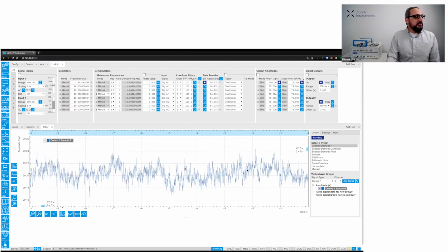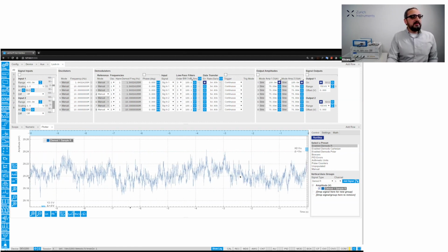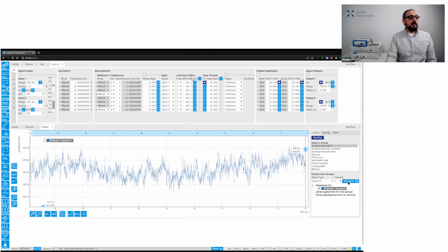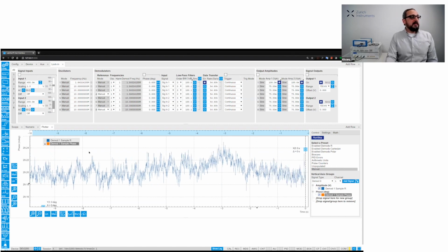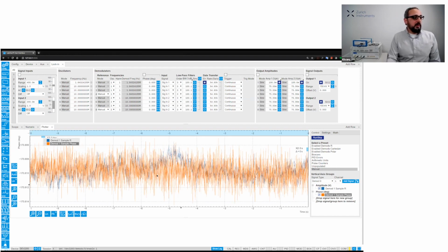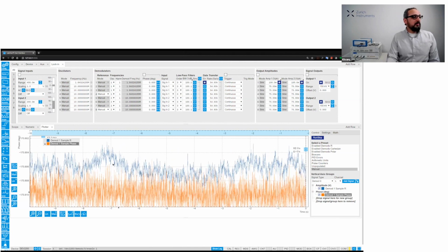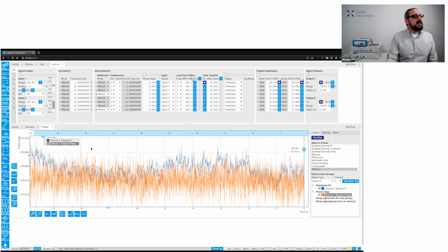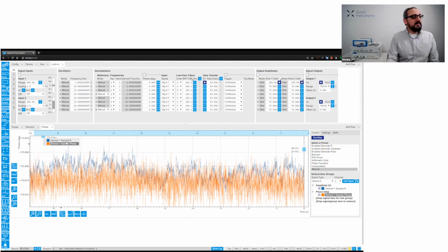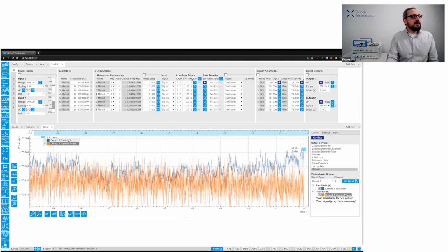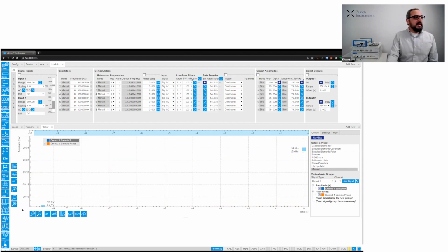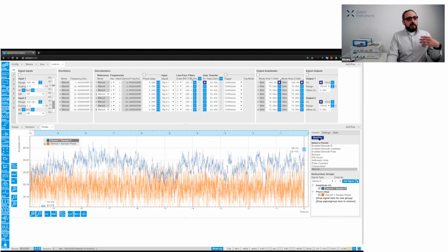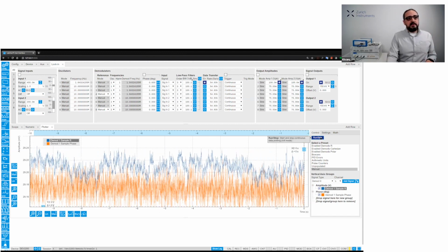So this is the plotter tool now. I'm looking at the real-time data. Now we can also activate to plot the phase, for example, in the same figure. Just not to get confused, I'm overlapping 2 measurements on top of each other, which have different units. So basically how it works is if you activate phase here, you see the phase in this y-axis. If you activate R here, you will see the amplitude.